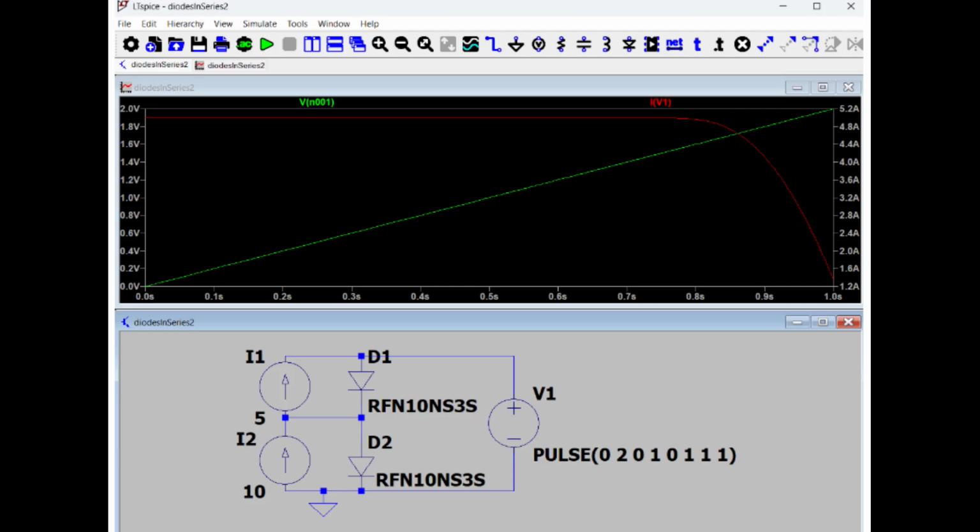There is also one more challenge with individual solar cells wired inside a solar panel. If you put many cells in series, the weakest one's current determines a string's current. Each silicon cell only delivers about 0.6 volts, and many are wired in series to get the panel's voltage up to around 20 volts or so.